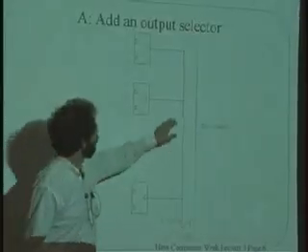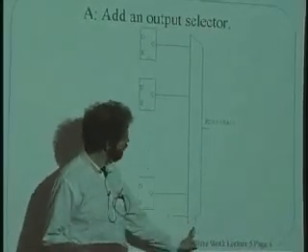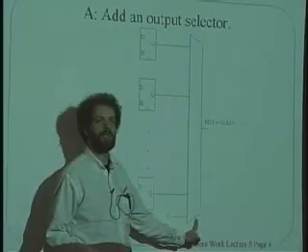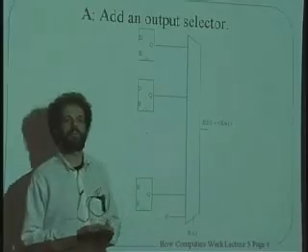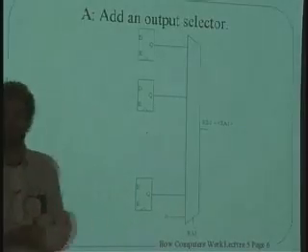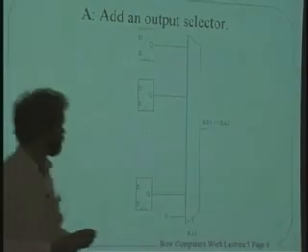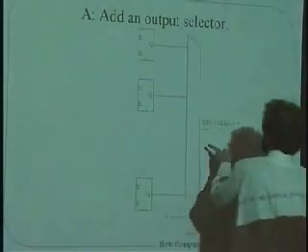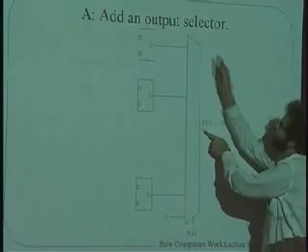It's called a selector or a multiplexer. And into the control input of the selector come 5 bits. And they specify one of 32 possible combinations. And those combinations each stand for selecting, as a data item to be steered to this output, RD1, one of the 32 possible registers.